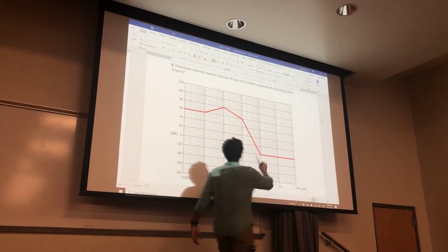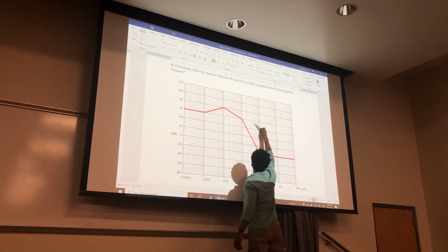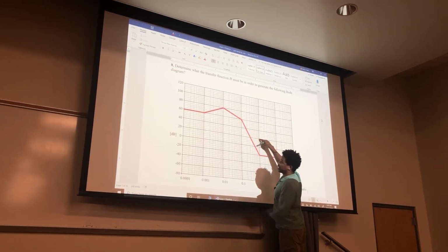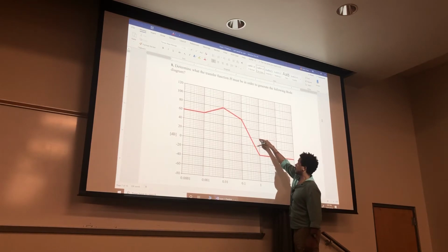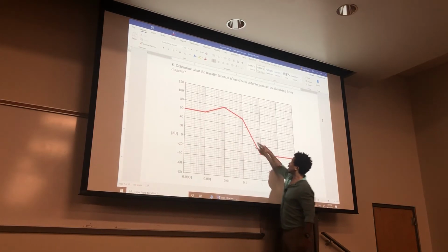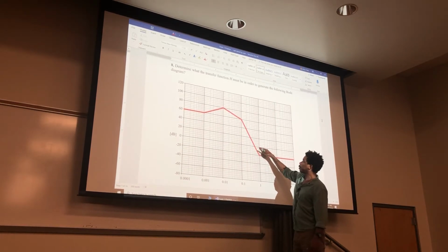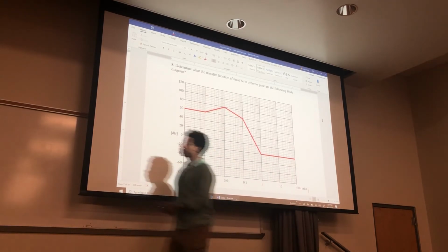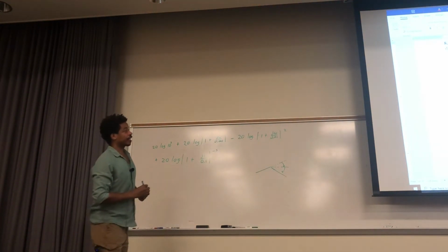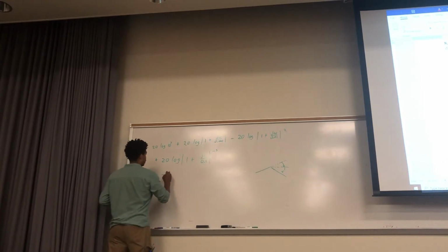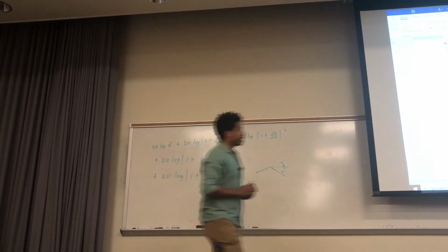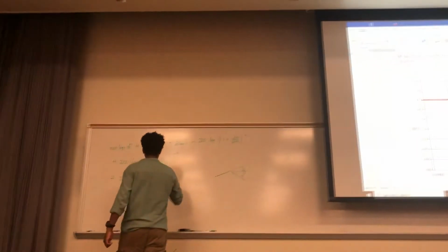Because if we did nothing, it would go off like this. If it went just down to here, that would just be -1. If it went down to here, because remember, this is a decade, if it went down from here to here, that would be -2 for the power, but it would have an extra one, so that's like -3 for the power, right here. And then the last one, that's a positive power. The cutoff is 1 radians per second.